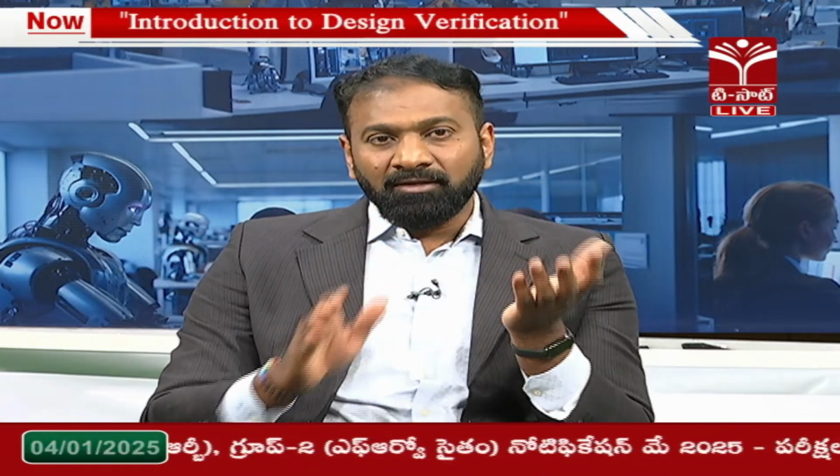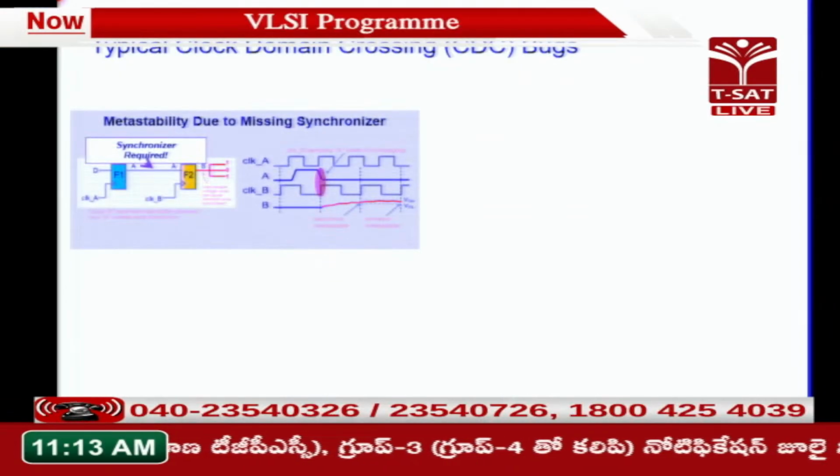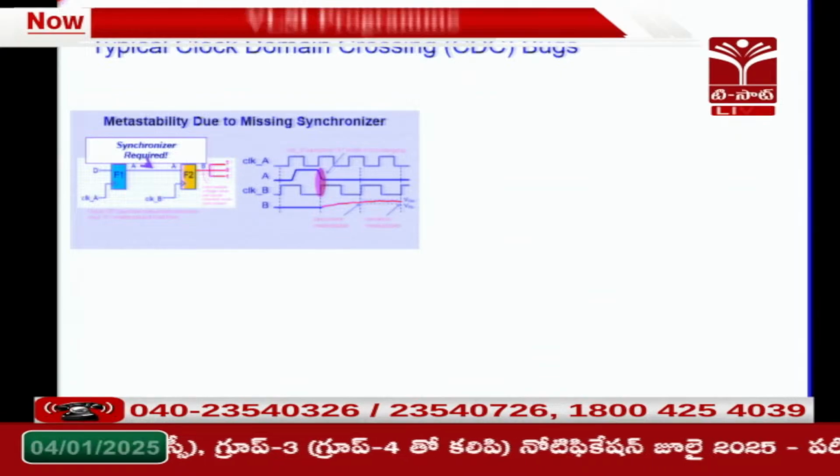So, that means different portions of the design may have different clocks, and now we want to verify these different clock domains. We want to ensure our data is able to progress from one clock domain to another and is able to synchronize. So, how can we achieve that? By using clock domain crossings. These are the issues which you can observe in terms of clock domain crossings.